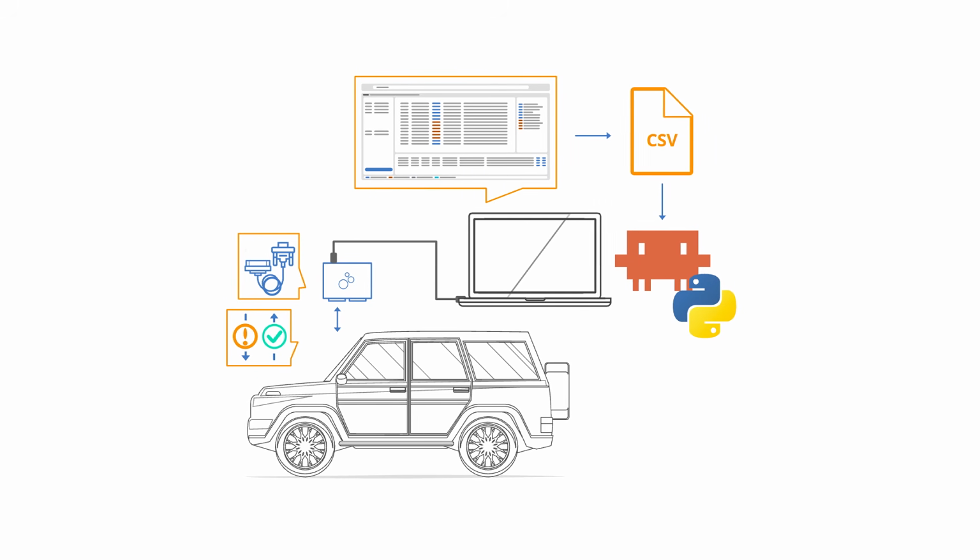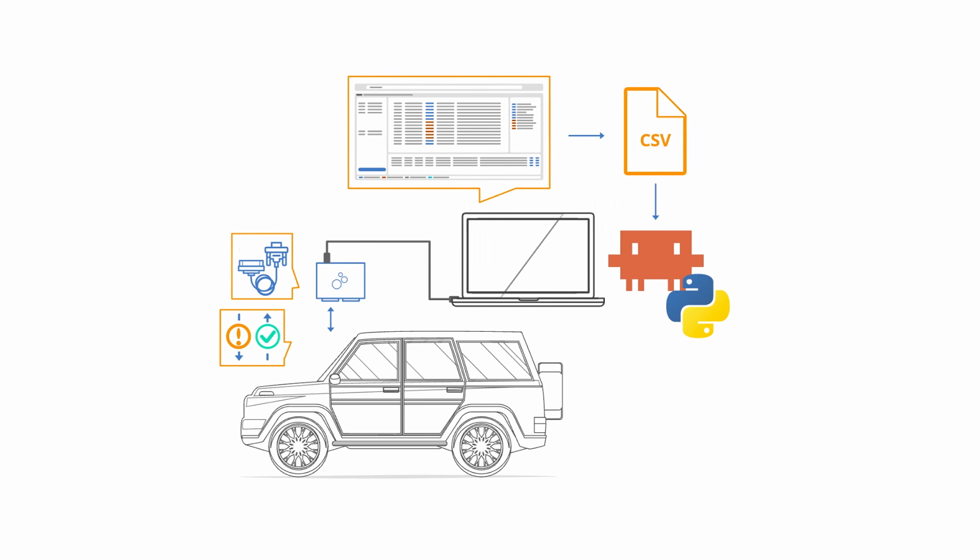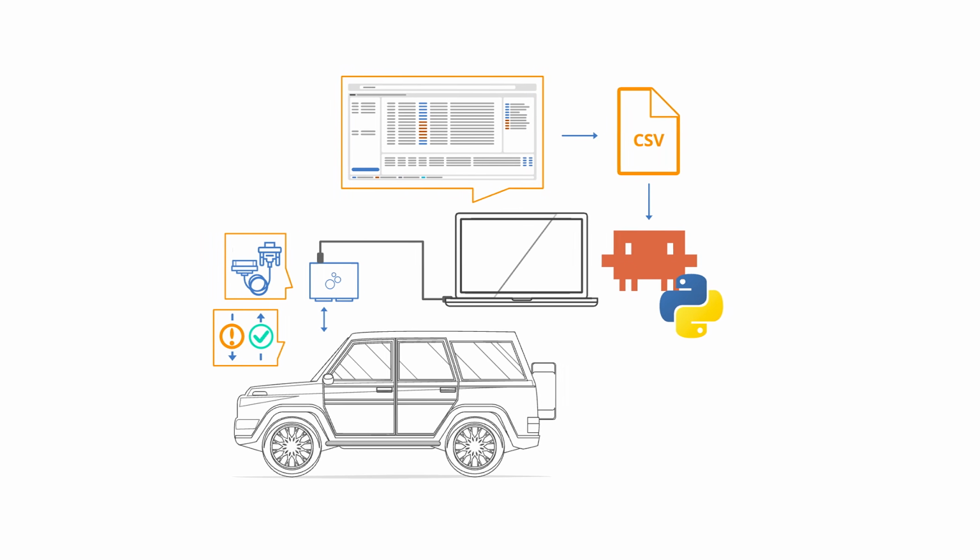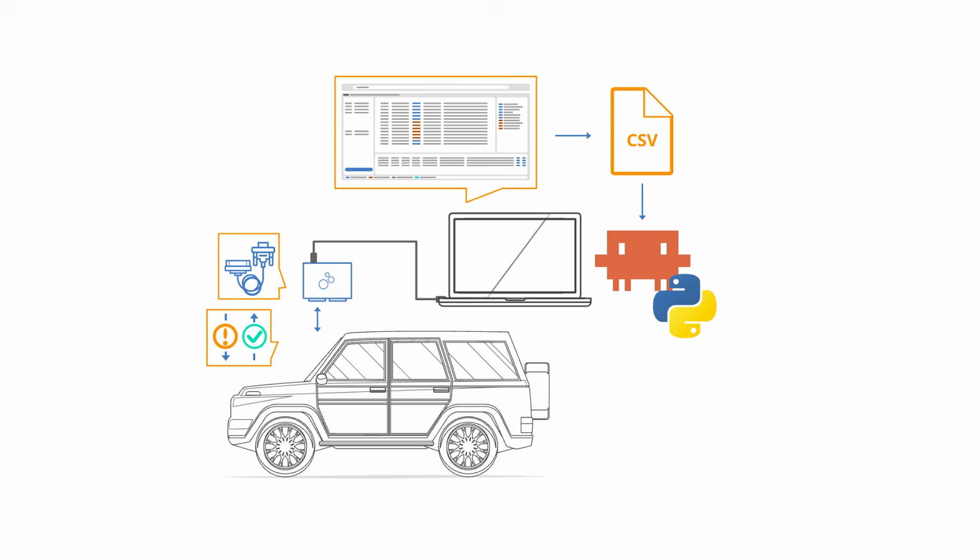Since you don't have the decoding rules for the CAN bus, you need to provide a reference signal that closely correlates with the signal that you are targeting. If we take speed as an example, the ideal reference signal for a proprietary speed signal in a car would be if you have access to the OBD2-based speed. That is because, as I explained, OBD2 is a standardized protocol across cars.